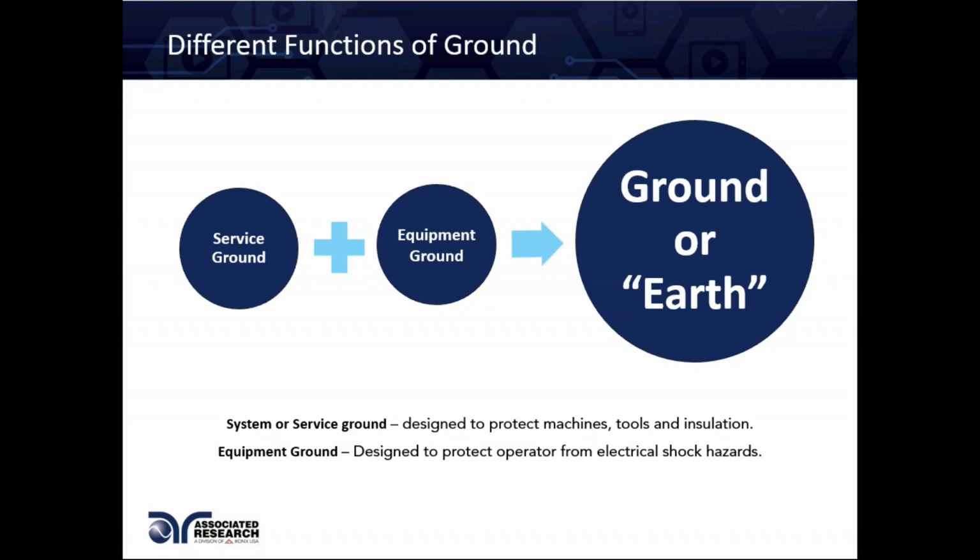So based on all this, we can imagine how important a ground circuit is. And I know there are devices that are not grounded, but then the lack of ground is made up by reinforced insulation or double insulation, making sure that the product is still safe to use or operate. And this also gives us an idea of why it is important to test the ground circuit of a product and make sure that the ground is continuous, as well as capable of dealing with any fault currents and routing them back to earth ground.